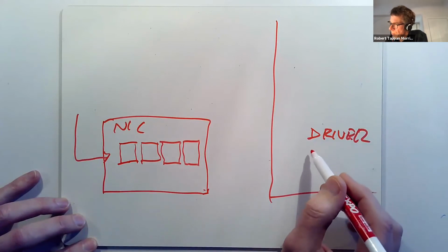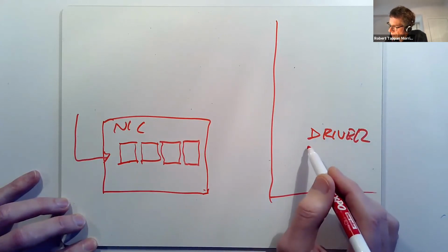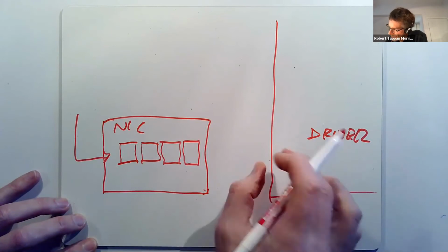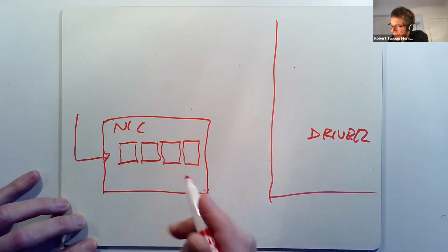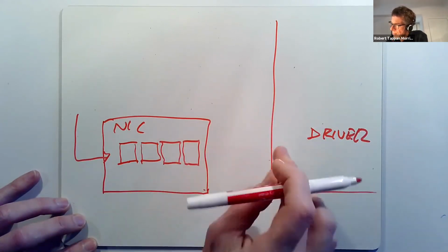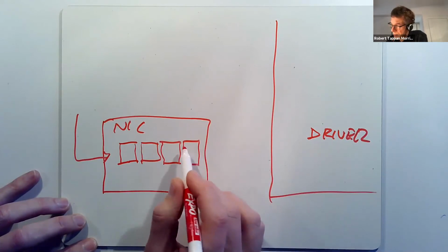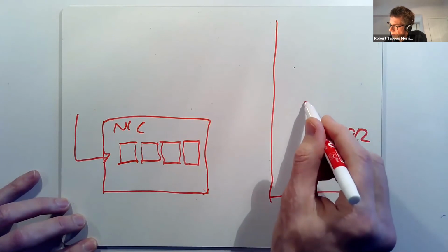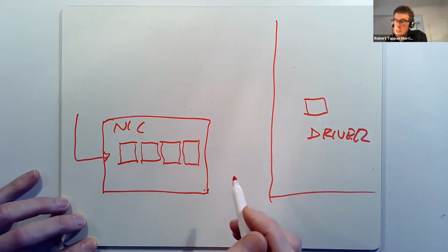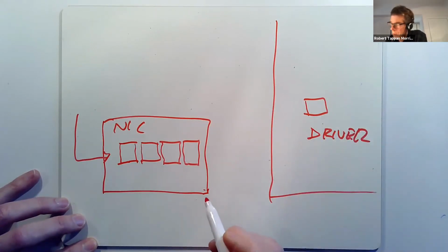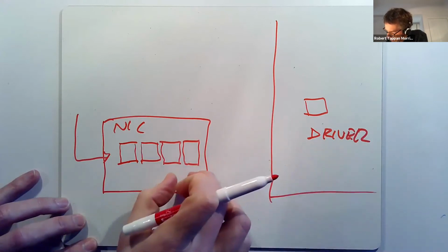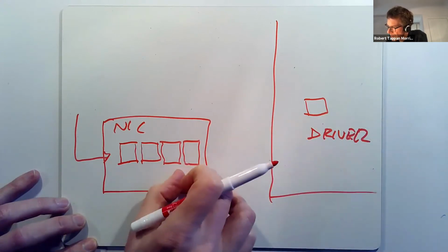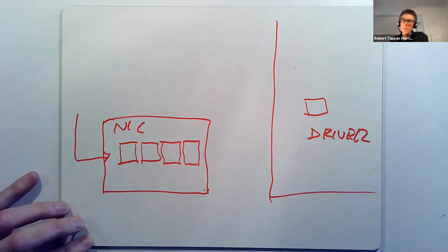Then in the interrupt, the host driver has a loop in it. The host driver will talk to the NIC and ask, you don't have any packets buffered? And if it does, the host has a loop that'll just copy, byte by byte or word by word, this packet into the memory of the host and append it to a queue inside the host. So that's how the paper's NIC works. The driver is responsible for doing the copy from NIC memory to host memory.